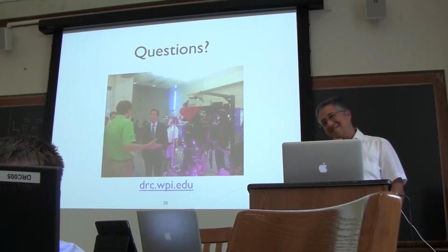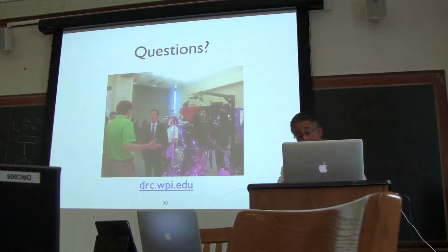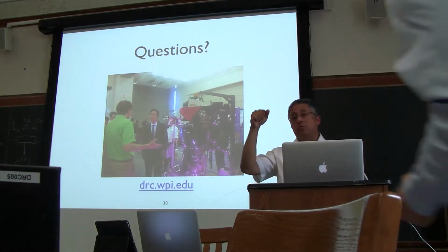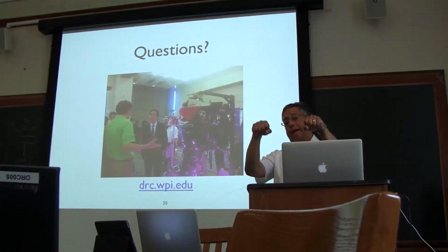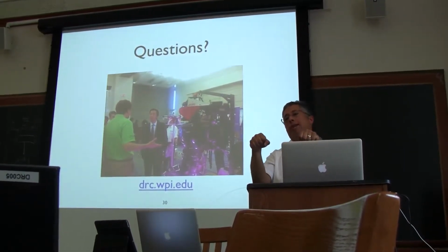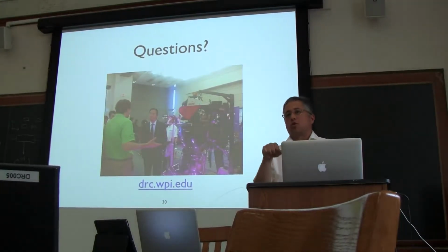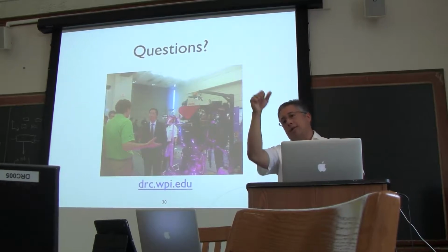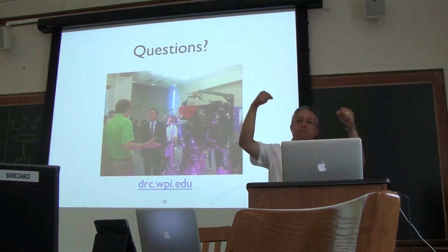Yes. So the ladder task, was that sort of scripted behaviors, or was that using your full body control and actually planning? It was using the full body control, and it was using scripts to position the hooks basically on the steps. And at that point we had the human intervention. We called it nudging. Through keyboard strokes, you can move your end effector position to position the hooks better, and as soon as you click OK, the robot performs another scripted task and then takes the step.